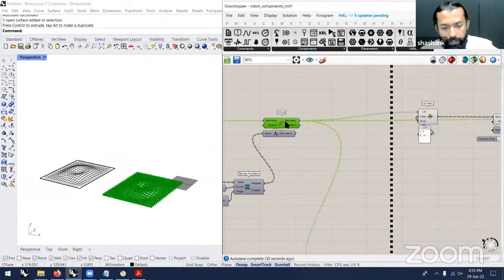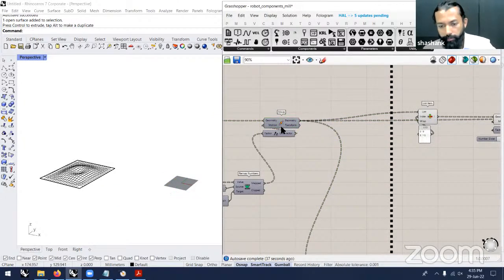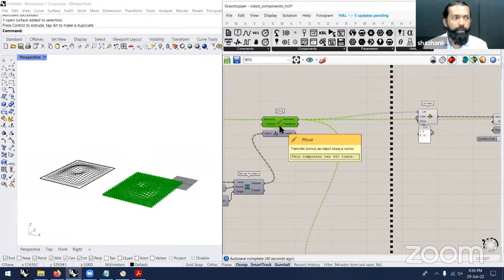So there are two components to it, but I'm going to let you all try to figure out one aspect of it. The first stage, if it's a big sized material that you're looking at, you might have to remove layers of it. The first stage is roughing, where you cut quickly all the bulk of the material without paying much attention to the finishing, and you chop off the bulk of the material quickly. So that aspect is called roughing.